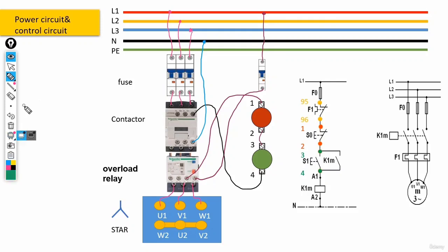And don't forget these two contacts, 13 and 14. These two contacts should be connected to contacts 3 and 4 in our start push button.